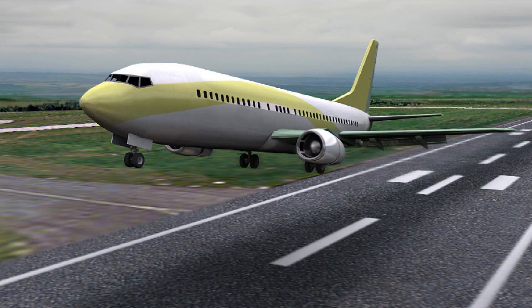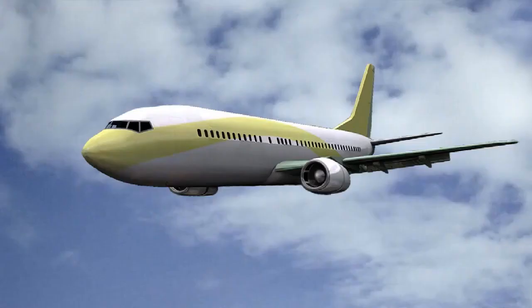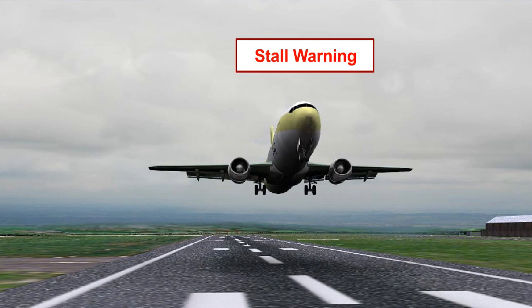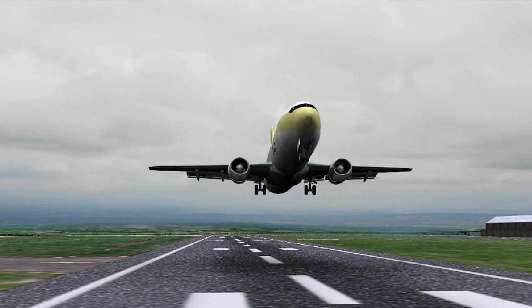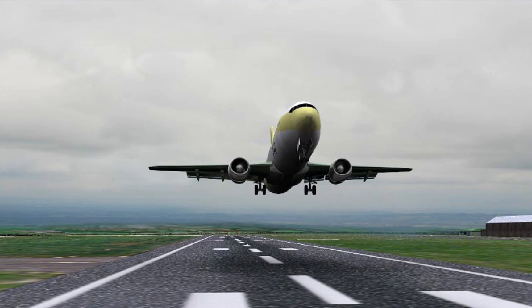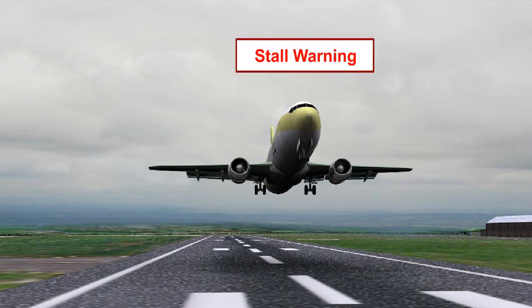The instrument is essential where precise control of speed is required, particularly on an approach path or climb out, and for realizing optimum performance in the cruise. The angle of attack indicator will also give an indication of an impending stall, and in advanced aircraft systems the angle of attack indicator will form part of the stall warning and prevention system.